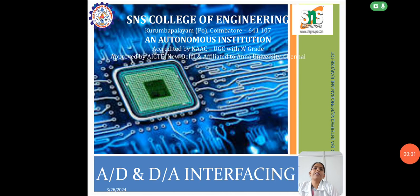Hi students, today we are going to discuss the D to A and A to D interface. Before getting to the interface, we have to know what an A to D converter is. The function of an A to D converter is to produce a digital word with respect to the magnitude of some analog voltage or current.